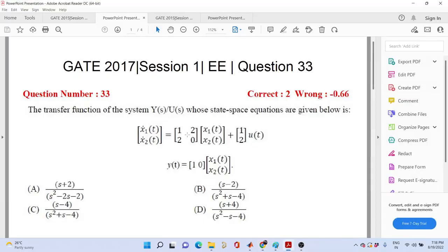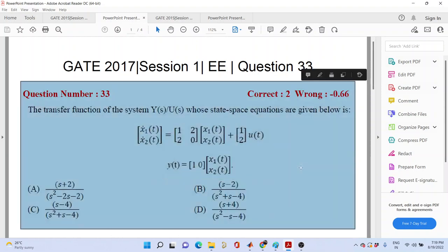Okay, so look at this matrix. The product of the two poles would be the determinant of this matrix. The determinant is negative, and the summation is positive, right? The sum of the two poles is positive, whereas the determinant is negative. That is, the product of the two numbers is negative and the sum of the two numbers is positive. From here, can't we say that one of the poles must be positive? I was expecting that you people will answer the question. Okay, so that was my way of thinking.